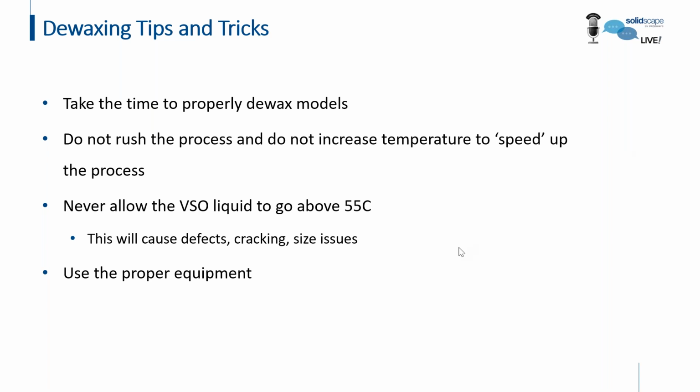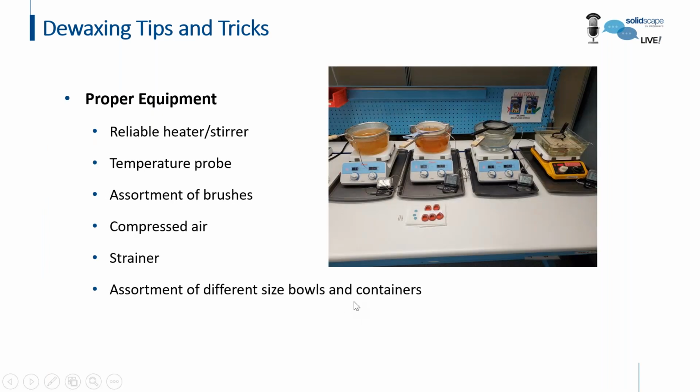All right, good afternoon, everyone. I'm just going to take a quick chance here to go over some tips in regards to the dewaxing. One of the most important things here, after you've spent the time printing models overnight, is not to rush the process during the dewax. If you heat things up too hot, you can have a lot of issues with defects, cracking, sizing issues, and it's also very important to use the proper equipment.